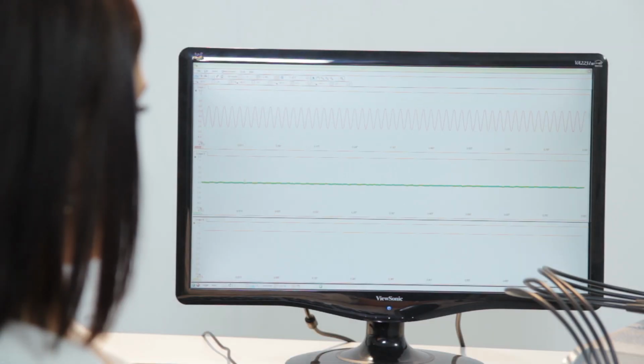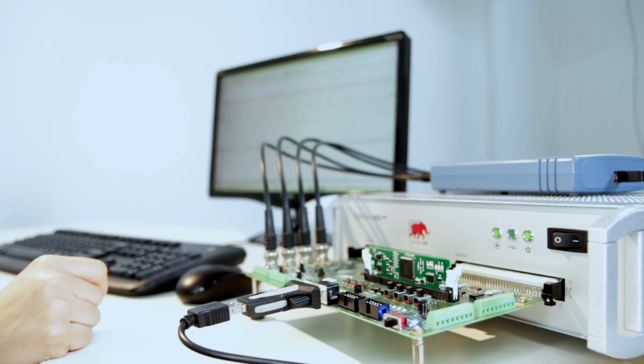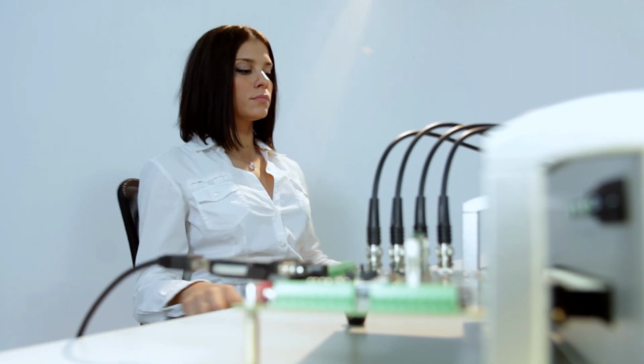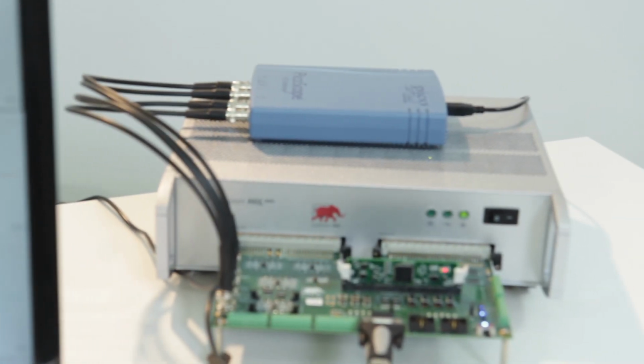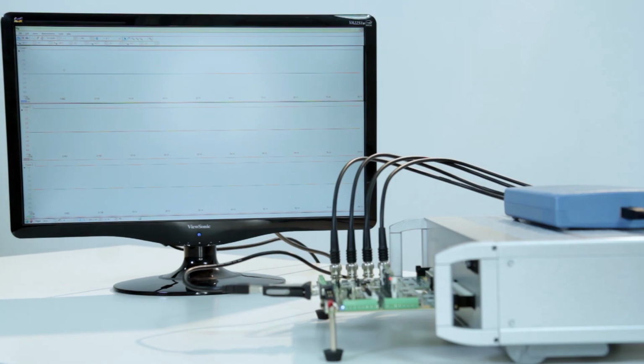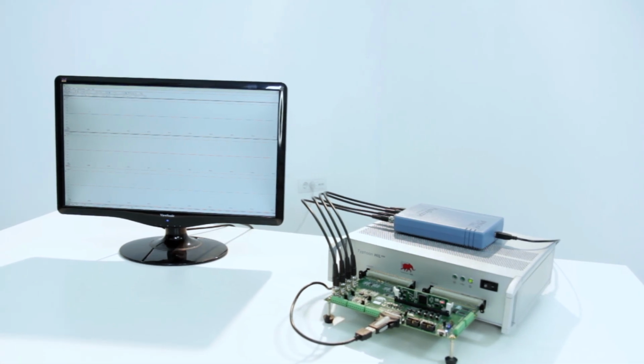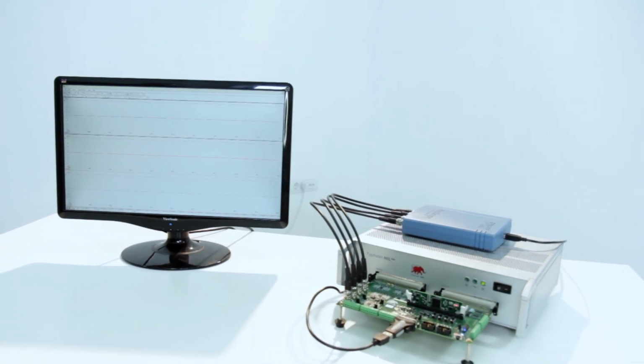of the phase voltage. Of course, we can continue testing our controller under all imaginable conditions, such as injecting sequences of harmonics, emulating faults, applying different load profiles, etc. Using the HIL 600 with the Python API, we're able to automate the process until we are satisfied with the controller's performance under all conceivable conditions, thus greatly increasing quality assurance.